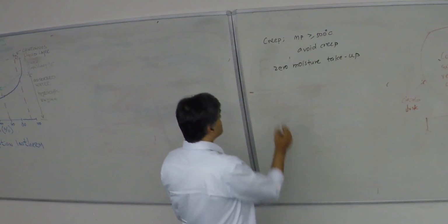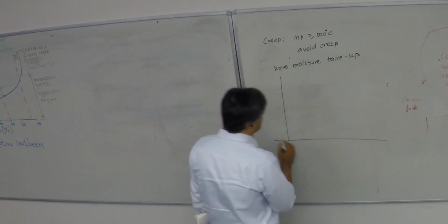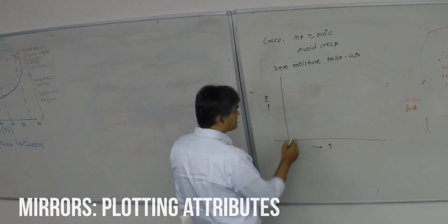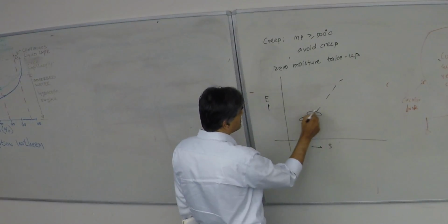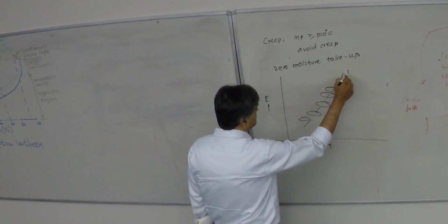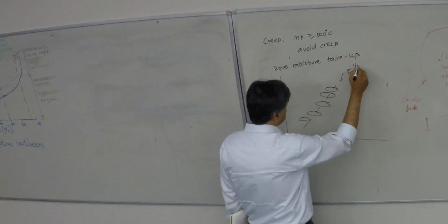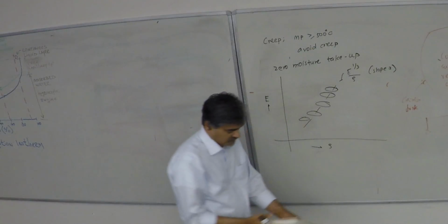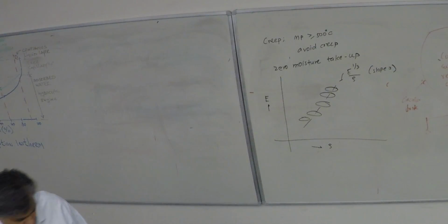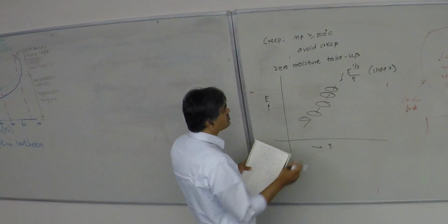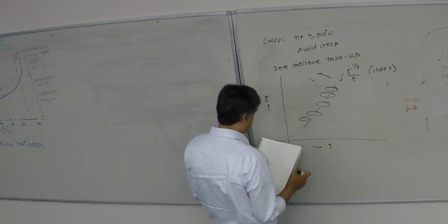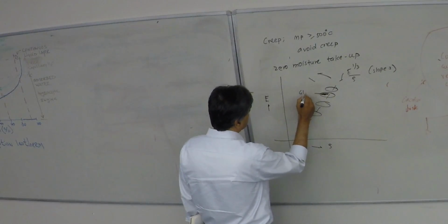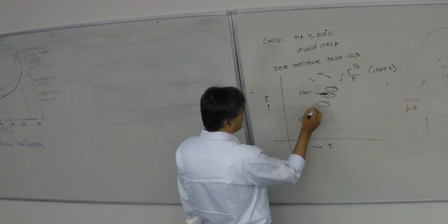So I want to get back to the software, but I think after this point I would invite you to plot the modulus versus density in the bubble chart like we have seen, for a slope of 3, and look at what conditions would appear. So you're looking on this side of the curve because you're trying to maximize these things. You'll see in this that glass comes to be somewhere here. So it is what is currently used.